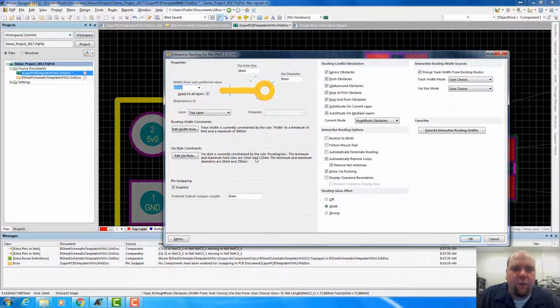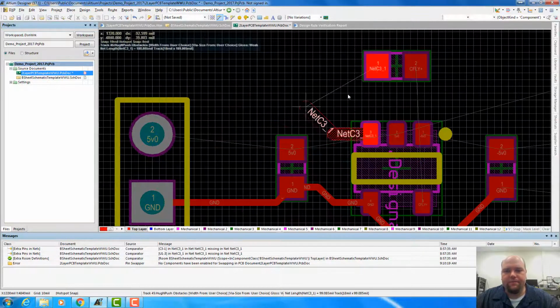So in this case, we have a width. The width is specified at 10 mil. That's probably okay, but we can probably go bigger than that. Now notice the limits of that trace width are going to be set by whatever fab you're using. A lot of low-cost prototyping fabs are limited to 6 mil, so you want to make sure not to go below 6 mil for these. There's also rules that you can set for your entire system that prevent you from going smaller than whatever the limits of your fab are. Let's just change this for now to 18. And that looks good.